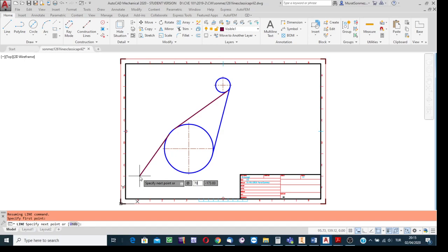Well, in such a case, not by clicking on the tab key. If there were arc simulation, then just by clicking on the tab key, we would teach the software that the first written number is the length, and the second number is the inclination angle. But here it is not the case. In this case, to teach the software that the first number is the length and the next number is the angle, click on another key on which we have the less than, greater than symbols.